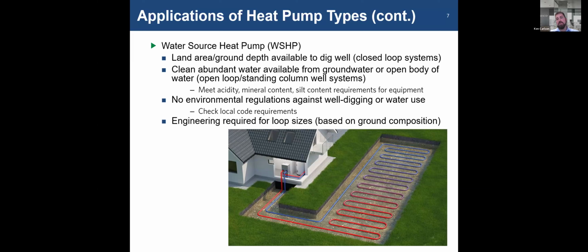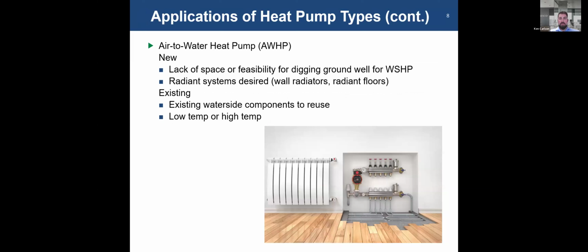The majority of the heat pumps that we're going to see being installed in most homes are probably air source heat pumps. And typically that's what we'll focus a little bit more on throughout this presentation. So we did talk about air to water heat pumps. So basically, a heat pump used to generate hot water throughout the dwelling. New construction, you've got options. You can put radiant flooring in. You can have a low temperature system. You can utilize a heat pump, potentially with a boiler backup if needed for capacity.